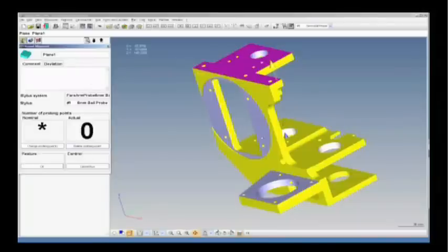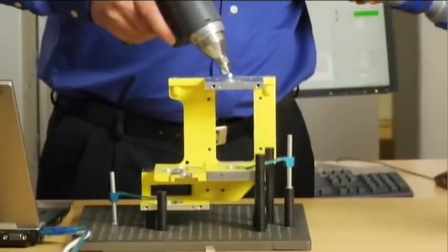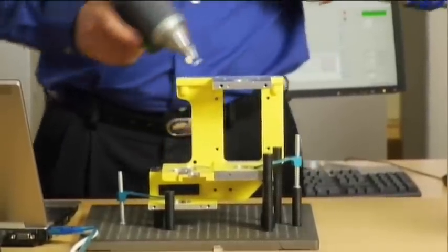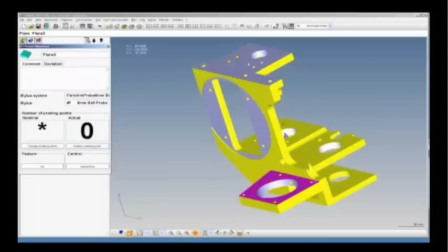So to calculate perpendicularity, it now needs information on the top. Sure. So with that, I can move around here and capture 740 points. Accepting that, it's just going to start walking me through the measurement plan. The next thing was parallelism. It's already measured the top one. I don't need to repeat it, but it does need some information down here at the bottom.